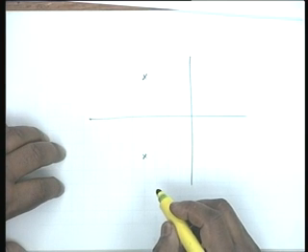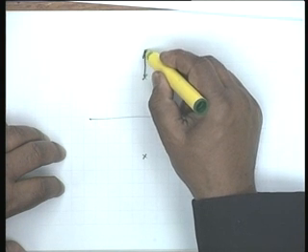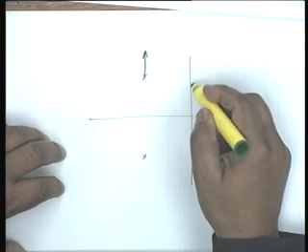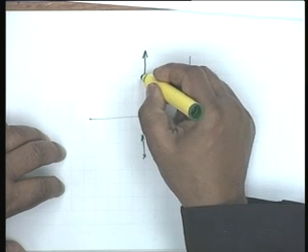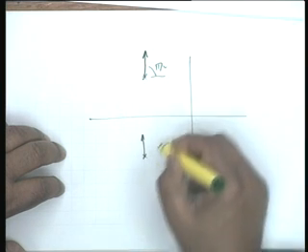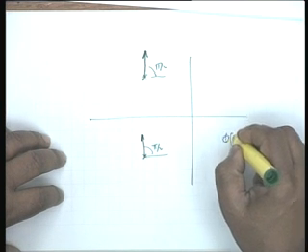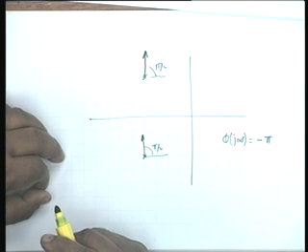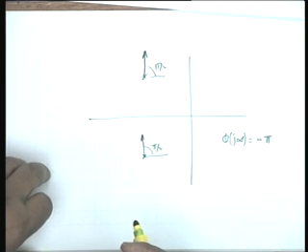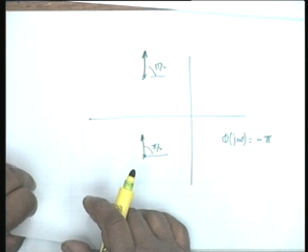If you have two poles like this, when omega goes to infinity, the vector becomes parallel to the j omega axis, this vector also becomes parallel to the j omega axis. So this angle is pi by 2 and this angle is pi by 2, and therefore phi j infinity shall be equal to minus pi. Agreed? Minus pi. So it starts from 0, remains negative and goes to minus pi.